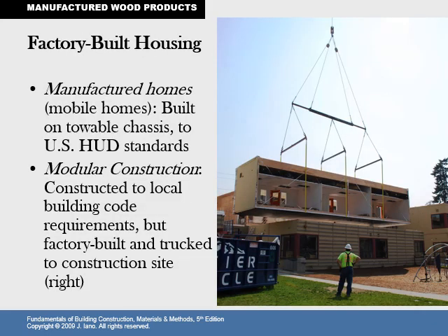Factory-built housing, manufactured homes built on a towable chassis to U.S. HUD standards. Modular construction to local building code requirements, but factory-built and trucked to the construction site. So this is a handy solution. This is the future because we can make the house and structure within the confines of a factory environment, meaning all the connections are well thought out, and in this kind of condition, you can really work on the details. But again, expensive because you do have to haul it, you do have to lift it into place.